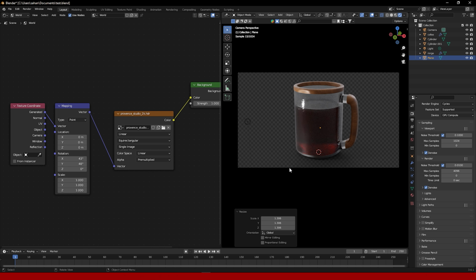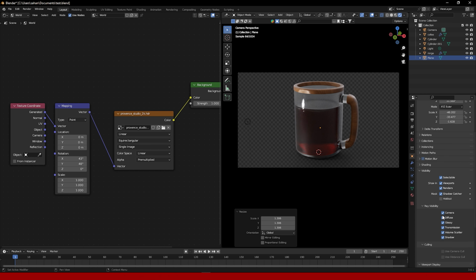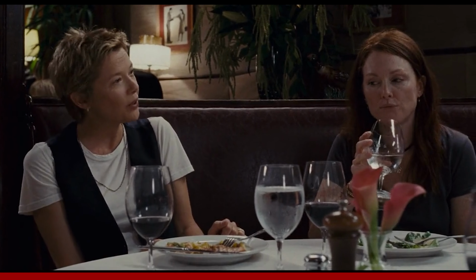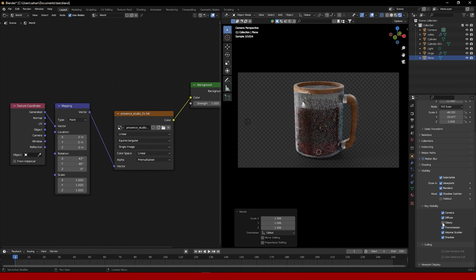So now you can render this mug, and after you can add background colors, background images, and this is completely transparent. You can change anything, but we need to use external software like Photoshop. In this case, I will teach you how to make it in Blender. Oh, and do you know that we're compositing now? It's compositing, so we're gonna composite this frame in Blender using Blender compositing nodes.